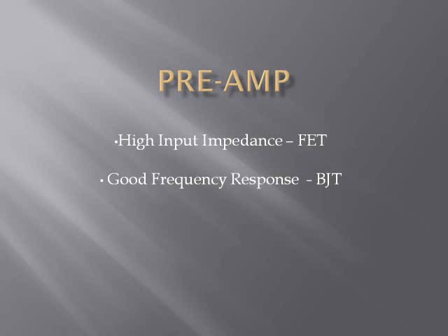The group's first step was to design a preamp. A preamp is needed to increase the input signal, in this case a microphone signal, to the line level strength required by the load, or in our case the power amp. It does this by providing stable gain while preventing induced noise that would otherwise distort the signal.